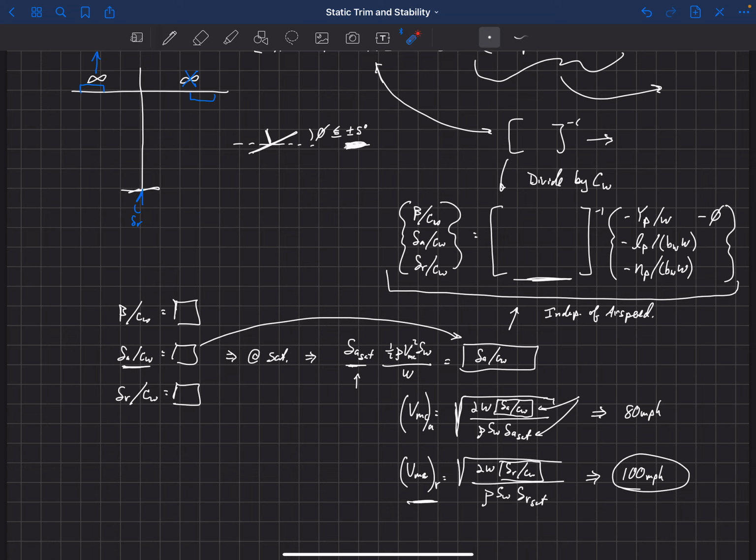The reason is that weight is offsetting some of the control required through the bank angle, and we're limited to plus or minus 5 degrees usually for this design. So the heavier the aircraft is, the more offset you get for that 5-degree bank angle.